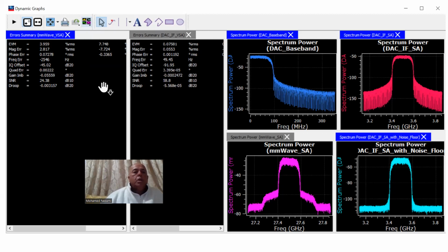This is the modulation analyzer of the PathWave, which I will show you in a minute, running live. And of course, this is the output of the PA. You can see here that the EVM really is about 7.7%. So we're almost right there. We said that we wanted, usually it's less than 10%. And then the QAM SNR in here is about 24 dB.